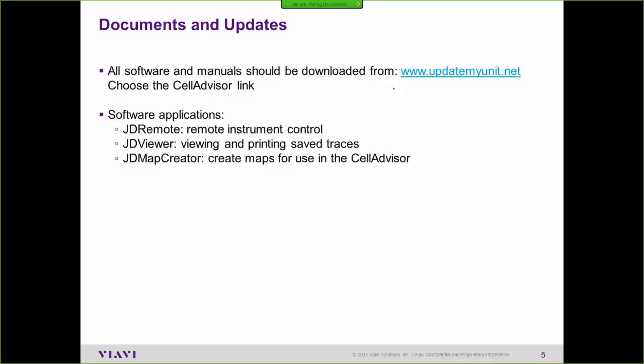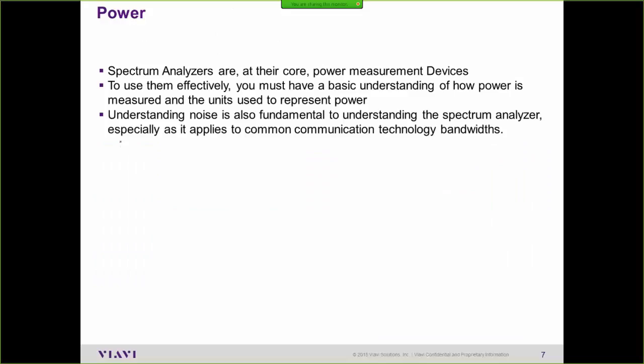And one of the problems that you have today is, in most cases, people just throw around power numbers kind of like they're quantities. And power is really not a quantity, it's a rate. So it's a quantity in the sense that it's a quantity of a rate. So it doesn't help when you're trying to understand what power is when somebody says 80 dB or 80 dBm or whatever it is, and they never really give you all the information around that, because power numbers, you have to know certain things about the number to make any sense of it. So we'll talk about that.